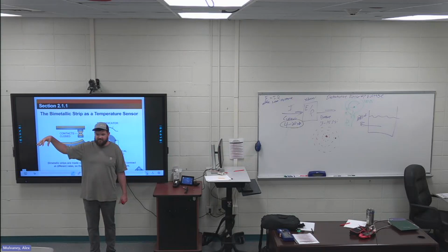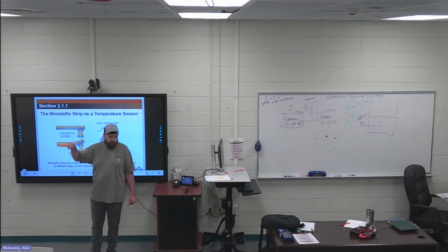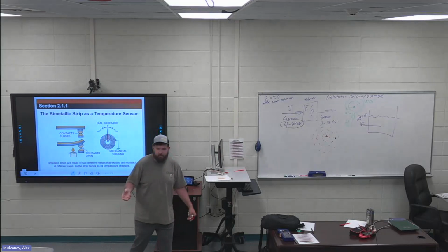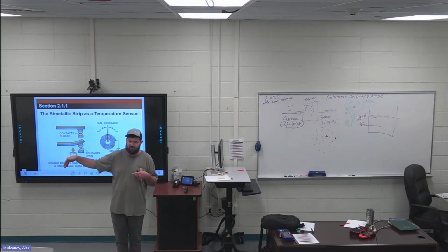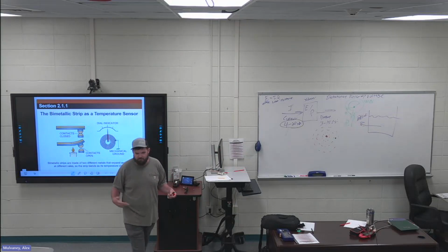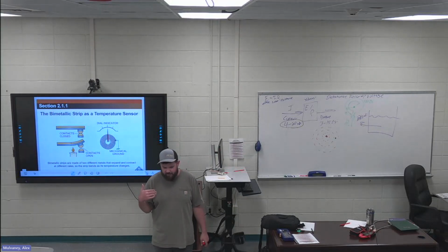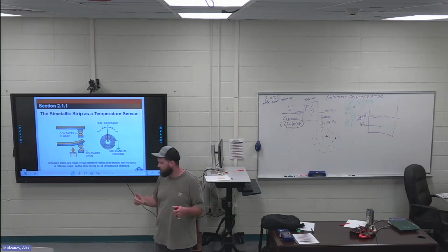And if I put a detector over there, most times detectors want real laminar flow. So you either have to put a flow straightener in, or the detector will say you have to go a certain number of pipe diameters past the valve to get straight flow. It's usually like 8 feet or something like that. But all of it is in the manual. If you have a globe valve, it's going to create turbulent flow. Either put a flow straightener in or go this distance away.